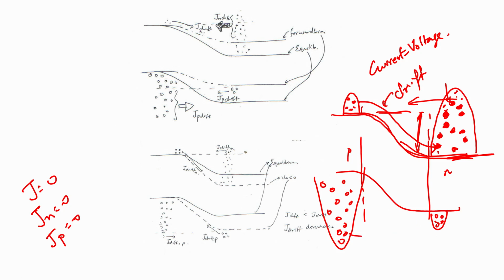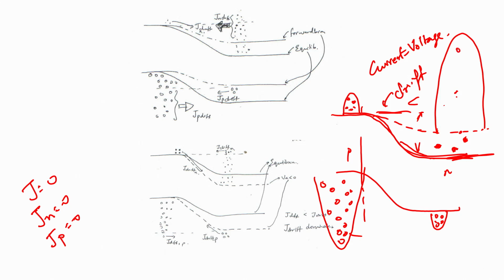But the moment I reduce the barrier height, so let us say we apply a forward bias, let us redraw this picture. The moment the band bending shifts to a shallower built-in potential by applying forward bias, this heap of electrons now protrudes significantly above this much lower barrier height, and a lot of electrons start diffusing from the n to the p side.